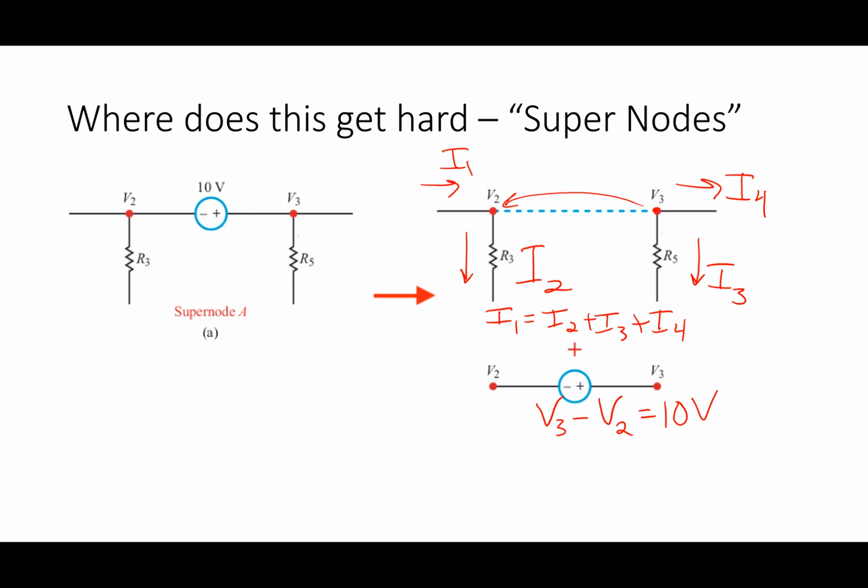Yes. A lot of people did not follow that on the first exam. I know that. This is one of the most confusing points in circuit analysis, but it's also an important one. If you understand this, then you understand it all. This is where weird stuff starts happening, because I'll see people write things like I1 plus I2 equals 10 volts. That voltage source really throws you off. The important thing is, from the analysis of the currents, it's as if that voltage source isn't there.